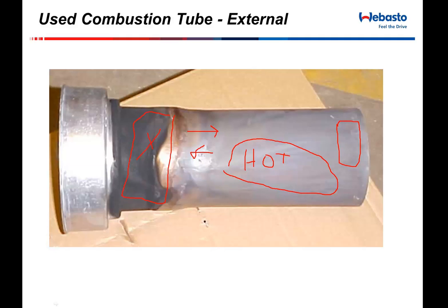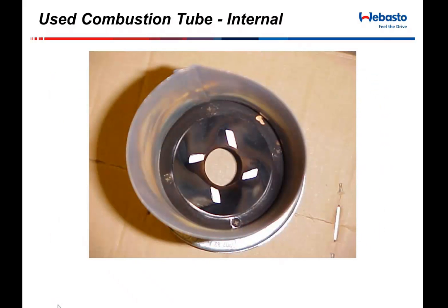If I look at the inside of that burner tube, I should see a nice circular, round burning pattern on the inside. If you're noticing a lot of carbon chunks built up on one side of it, what's happening is that the nozzle coming through the middle is squirting over in one direction. It's starting to become clogged and may be in need of being changed.